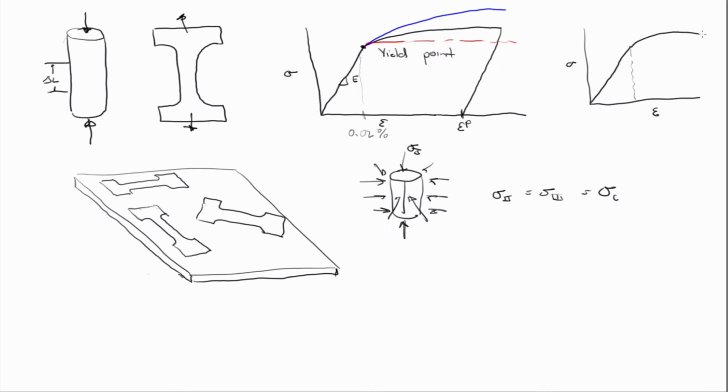So you will see some inelasticity, and the shape of the curve will be a function of the confining pressure. Typically, as you increase the confining pressure, the rock will tend to behave in a stronger manner. Okay, but I kind of ran out of space up there.